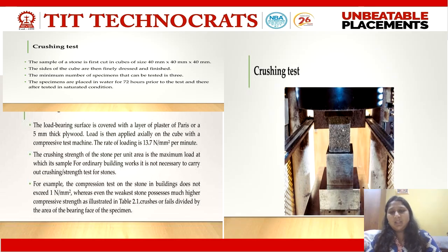Or I may keep two thin plywood sheets, one at the bottom and one above the top surface of the stone, so that when I apply load, it may come down in equal proportion. Then the ready stone is placed in the CTM machine, where we apply load at the rate of 40 Newton per mm square per minute.